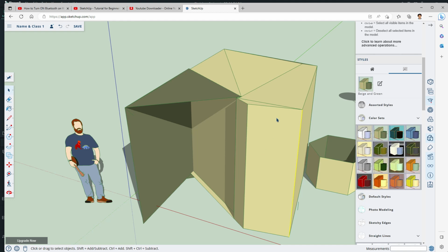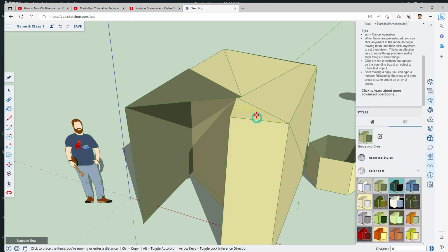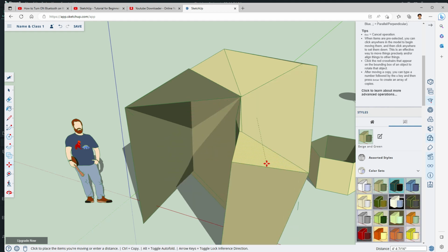So once you take the select tool and select the line, this, this, this. Suppose this is the selected line, and now you take the move tool, so it will convert 2D into 3D.